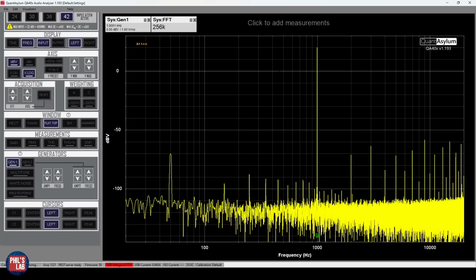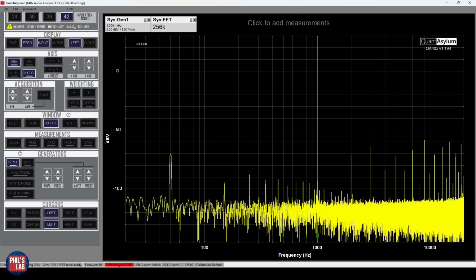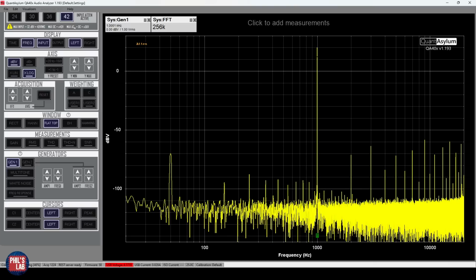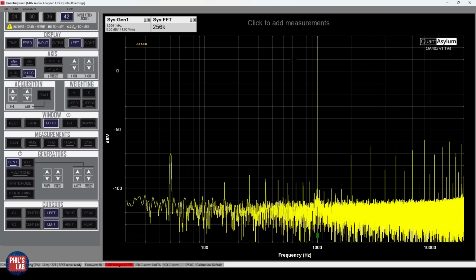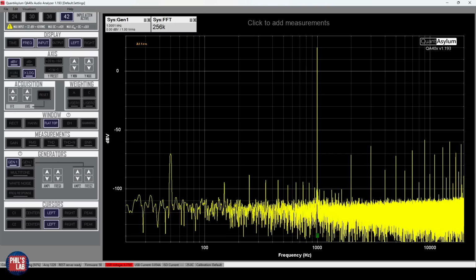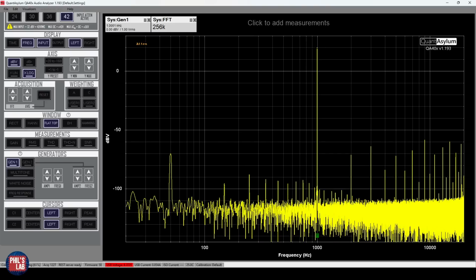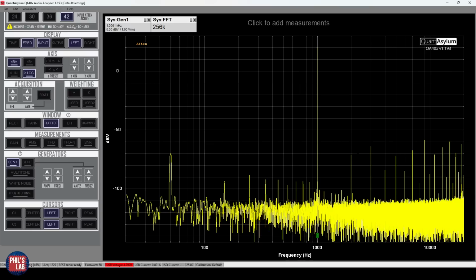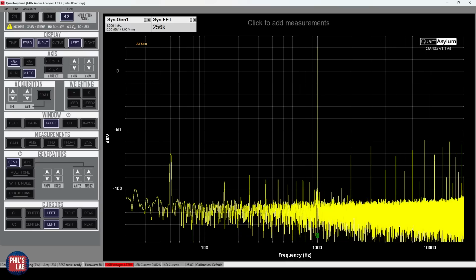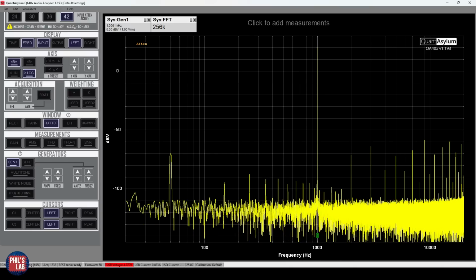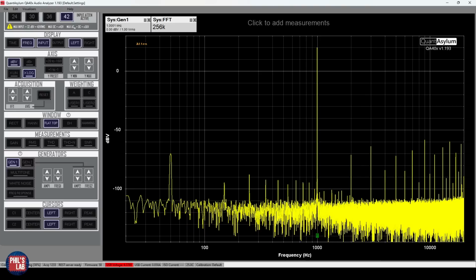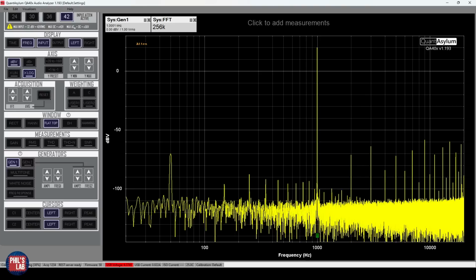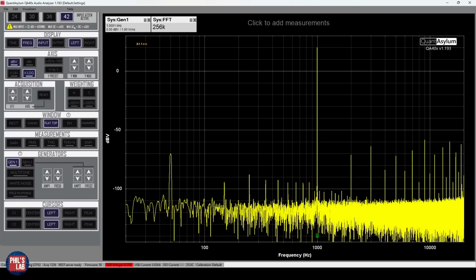in the frequency domain. What we can see quite clearly is, of course, our fundamental at 1 kilohertz, and that's going to be amplified by whatever gain we set. And remember, we set our gain to 20 dB. That's why we're getting 20 dBV at our output shown here. Some other artifacts we can see are due to non-linearities in this whole system. So you can see peaks on the bottom right and the bottom left, as well as some 50 Hz mains noise seeping through, which you can see in a peak on the bottom left. All of these peaks will add and appear as distortion.